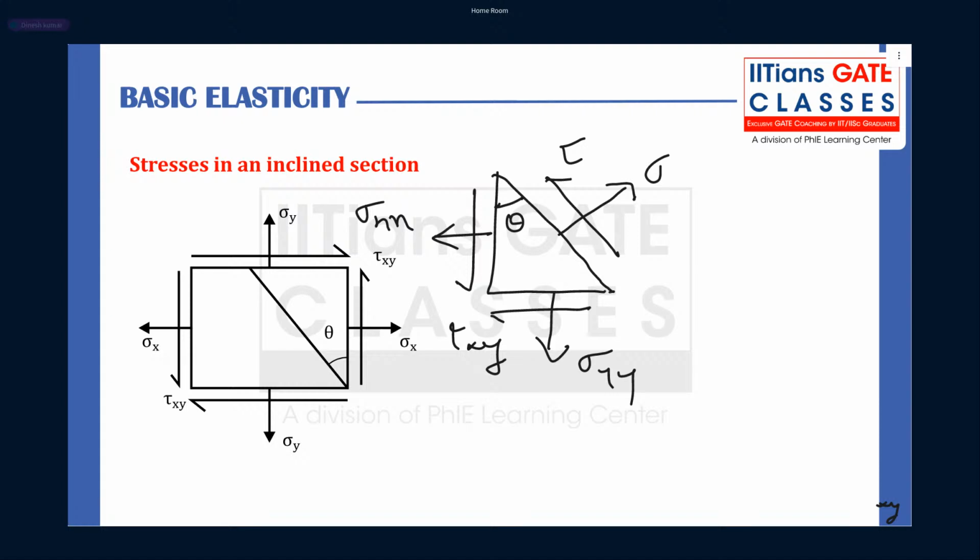Clear? It is not a biaxial stress system, Gopal. It's a 2D stress system. I will also tell what a biaxial stress system means. But in a 2D stress system, in strength of material Indian authors use this triangular element and find sigma and tau. Now tell me, guys, is this sigma, sigma T or sigma S?